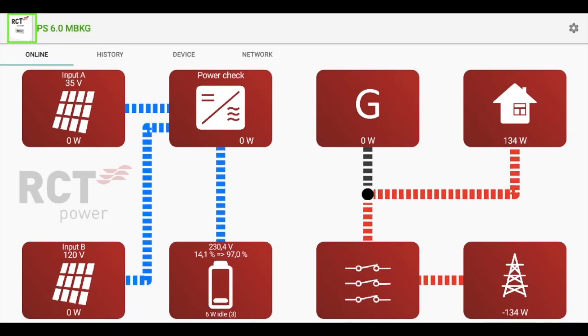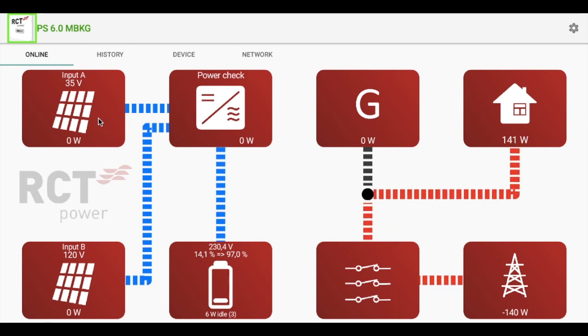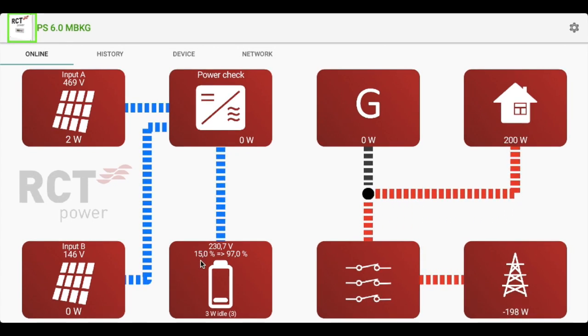Now we have situation, it's typical for winter night, where obviously we don't have power from sun and battery was discharged to lower limit. Battery has three limits actually. Charging limit, in my case set to 97%, and two discharging limits. In case that we are connected to grid, is used first discharge limit, in my case 15%, but battery can be discharged up to 5%.